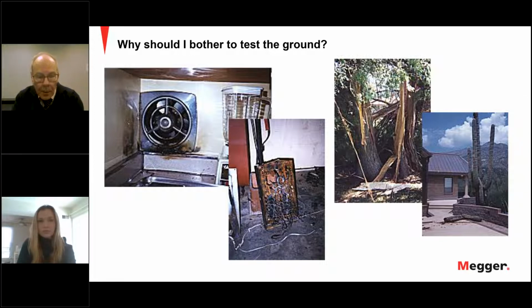And so fundamentally, that's the answer to your question. Why should I test the ground? Because it may no longer be there. And if you have a fault condition, then you don't have the protection that you should.